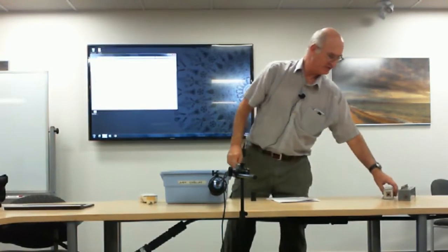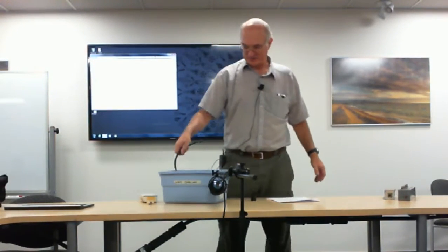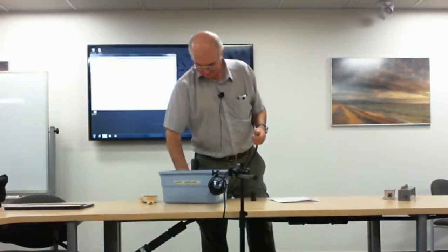There are a couple of other tricks that can be used for radio frequency interference. And this one's kind of funny. You know about resonant antennas. You know the quarter wave is the magic length for most stuff. Well, it's actually possible to create a filter by simply cutting a piece of coax a quarter wavelength long at the frequency that you're receiving, and it will actually give you a notch filter on or about that frequency.